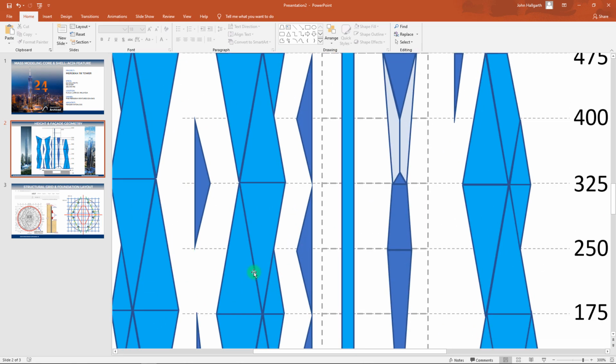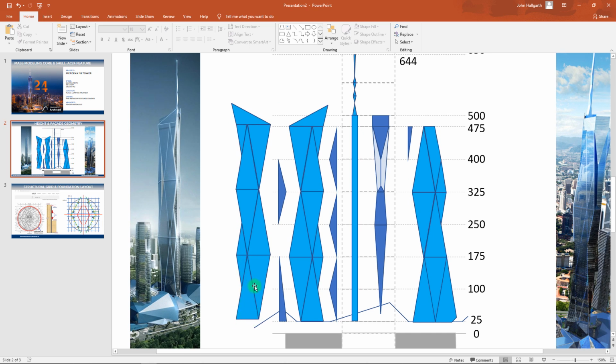And what I'd like to do is start with some triangles here that I think are going to give us a nice shape, because if we approach this by doing each different triangle with a morph, we can just copy it around and offset it so it's the right size to span the different tiers. I think it's going to make our lives a lot easier with how we can start placing this in, and we can adjust it around and shift it as needed. I think the biggest challenge is probably going to be where this facade matches up with this version of it over here, specifically right on this line. That's where we'll probably have to play around with it a little bit to get it to match up.